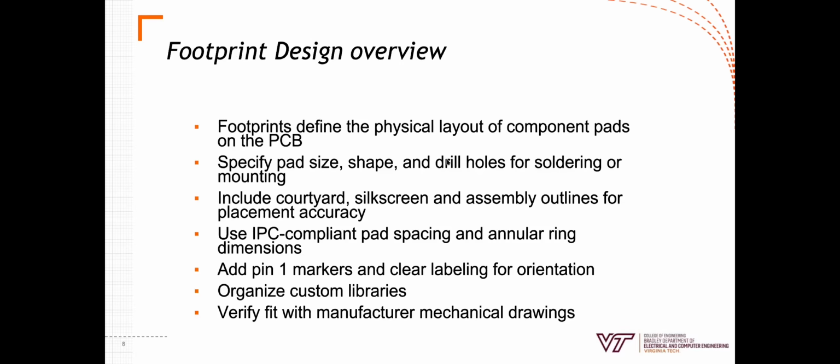Footprint design. Footprints are the actual physical layout of the chip that you're using and how it solders onto the board. So this is the copper pads exposed to actually interface from your PCB to the chips you want to solder on. You have to specify pad size, shape, and drill holes for soldering and mounting. And you need to look at the datasheet and the mechanical diagrams to actually draw out your shape and make sure everything lines up when you go to solder it on.